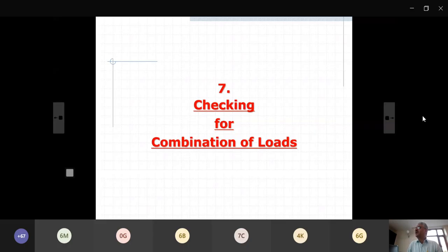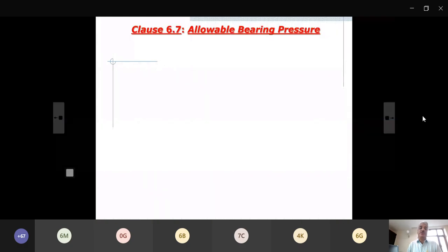In India, of course, we don't calculate. We also maybe, if you go to J&K, or in the northeast, some places like Tawang, where the railway line is going now, snow load. All these adverse things may not happen at the same time, right? Whereas we take all the loads or their combinations. So taking that probability factor, that every load may not happen at the same point of time, you give some relaxation when you check for combination of load.